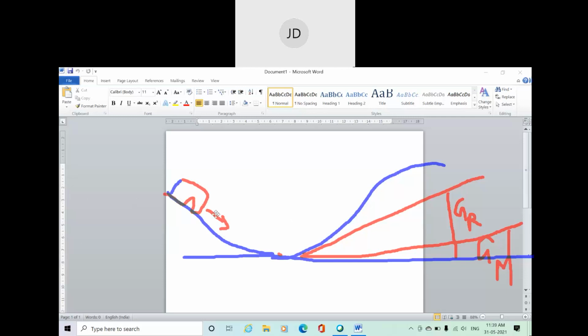And this train uses this momentum energy to move upward up to a certain level, and from that point a train can move smoothly over this gradient. That means the train uses the momentum generated during the downward movement to move up the upward gradient, which is actually more than your ruling gradient.